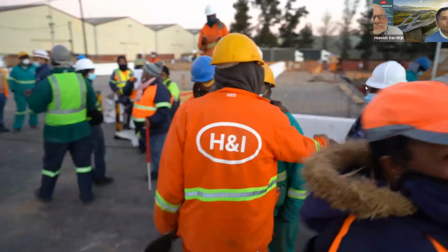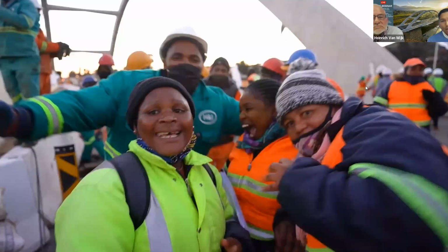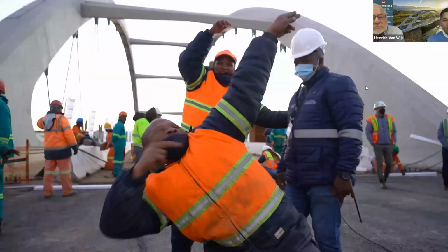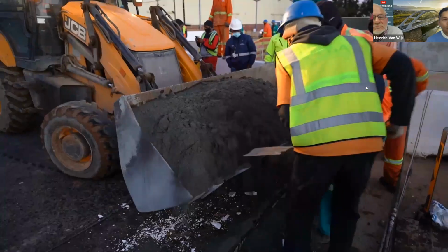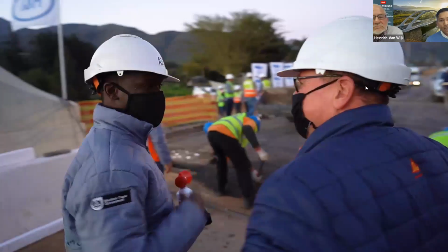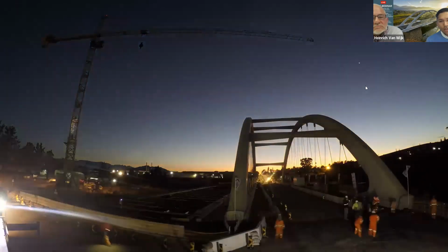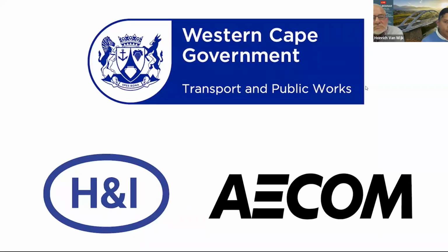And we used this mass information to update our model so that the self weight was accurate. And I think when your self weight is accurate, your cable force is directly related. The self weight of your structure is directly related with your cable forces. So that was one of the ways that we calibrated the model.